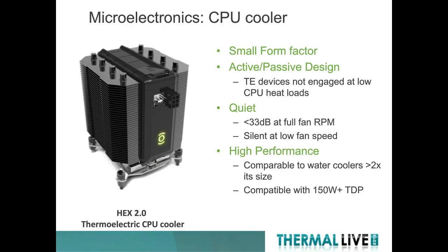So I think the take-home message for our listeners, especially the engineers and designers, is that when you design a thermoelectric system, you don't always necessarily have to size the thermoelectric part to take the heat load of the entire system. You'll see this in a lot of the systems that we design, this active-passive mindset, where you can allow part of the heatsink to act without power, without the thermoelectric device, and then the thermoelectric device can be used as a safety net, or in some cases to make sure that in extreme environments the device will survive, but you won't need to use that power at all times and in all environments.